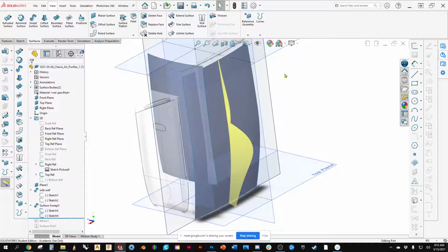It's kind of like having curvature between surfaces. If I'm doing curvature between a surface and its vacuum formed part, and it's 0.8 degrees off, I'm going to call that acceptable, because that's all that's needed. Now, if I'm doing automotive surfacing, no, that's going to be class A. It's going to be perfect. We're not going to want to see any of that anywhere. So that's really the difference with class A: the restrictions.